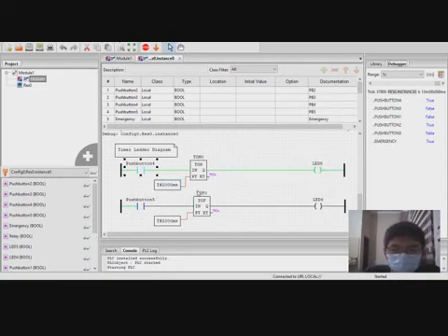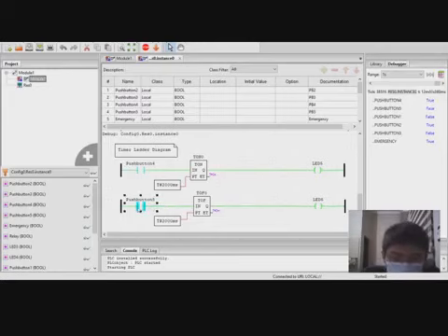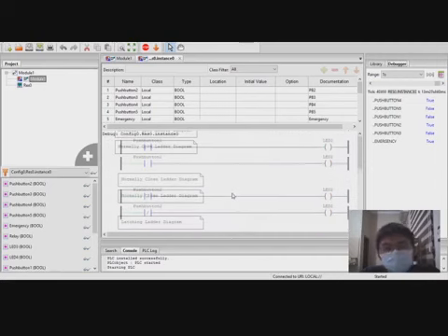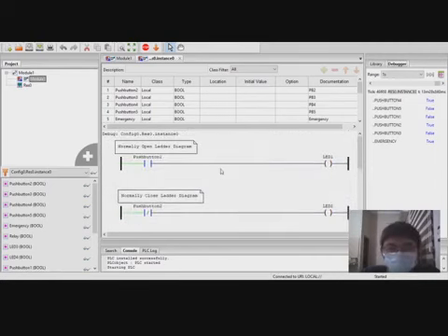And in the last line we have timer off. Let's see what it can do. When we give a true value to the push button, the voltage will flow from this line to the LED. Then when we give a false value to this contact, after 2 seconds, the LED will turn off. So this is the basic PLC ladder diagram in module 1.